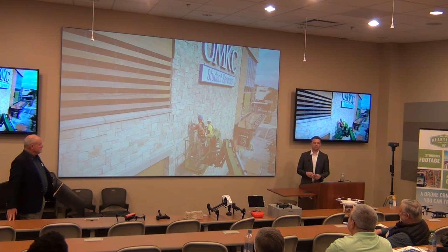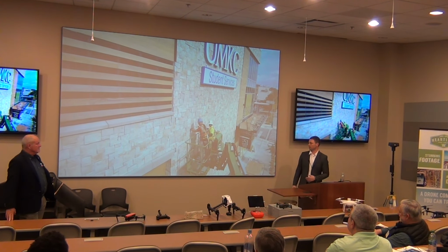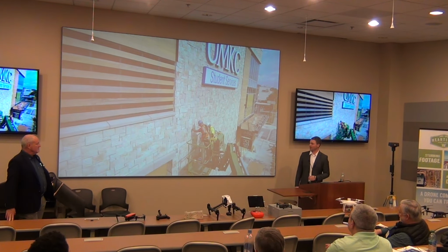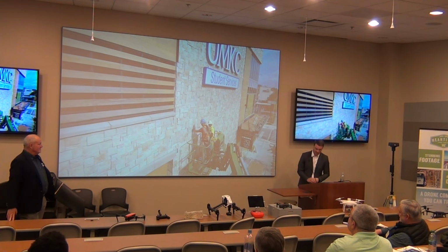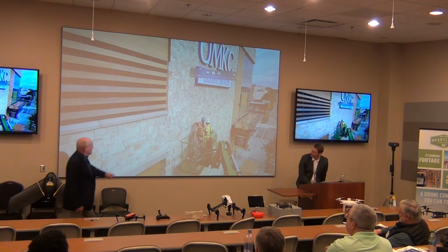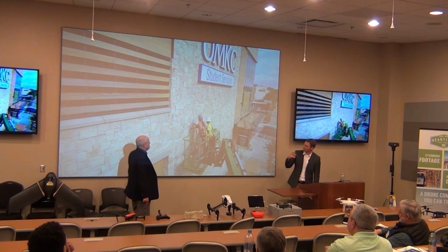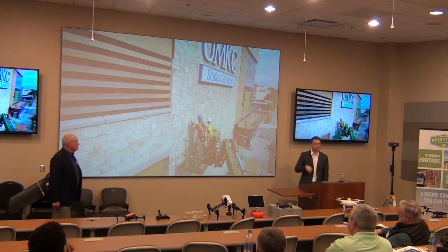And not only were we tapping on stones that were falling off in our hand, but in this case, this was 4 feet away, 3.5 feet away, and a stone fell off. And you can actually see in the void right there, after it falls off, you can see the scratch coat. Look in the void right here. Yeah, so you can see where the donut ring was at.